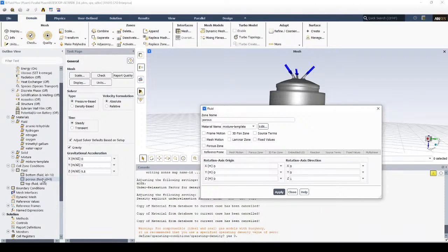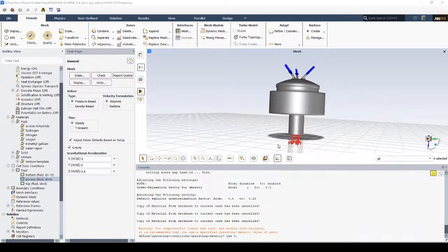In reality, the shower heads will prevent any flow in the X and the Y direction. It only allows flow in the Z direction. And there's a pressure drop because we're squeezing flow through very small holes. So we definitely want to turn on the porous media in this. And oops, where did it go?